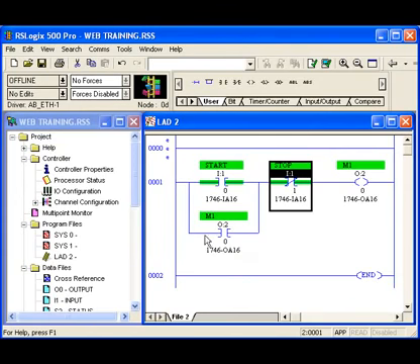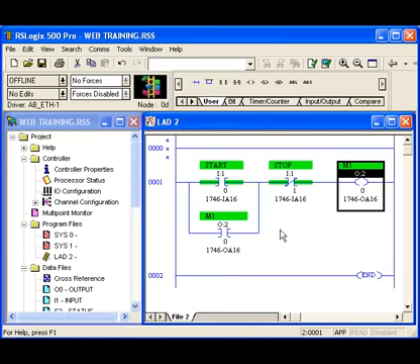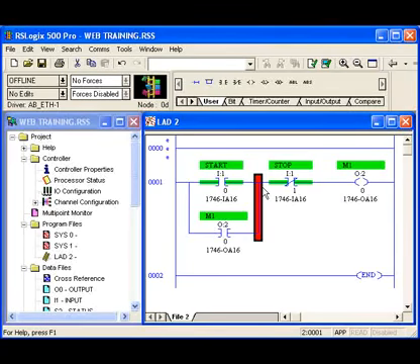I can use as many of these contacts as I need to take actions in my program. That's the beauty. I can't find a real relay with 100 contacts. I can't very easily have 100 relays in a panel and have to deal with the wiring and the maintenance issues. But with a PLC I can put 100 coils in here, have 100 outputs going to different field items, and take up very little space.